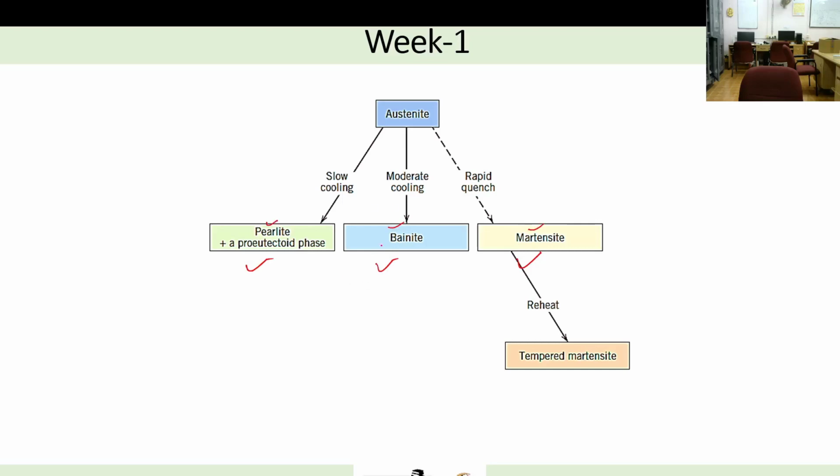Why I am telling the cooling rate here is because whatever microstructure you generate using any heat treatment, once you weld them, the temperature during welding will go very high, like 1000, 2000, depending on the material, the filler or the welding process that we are using.